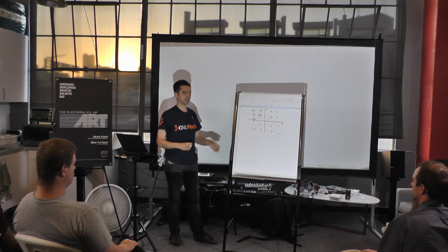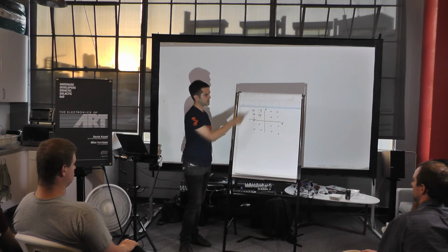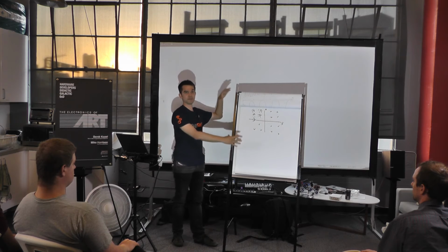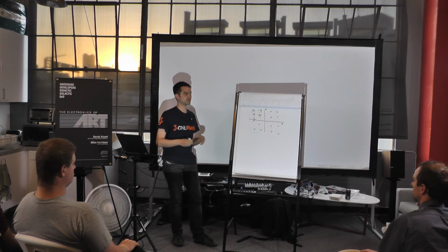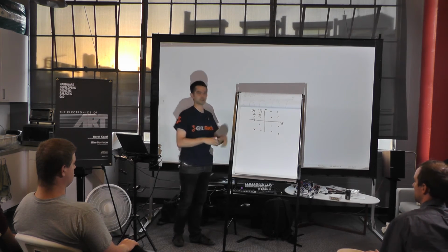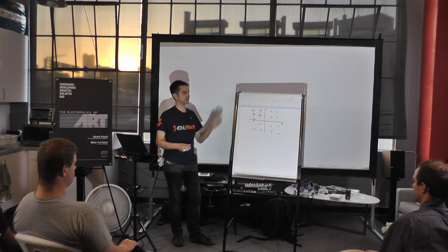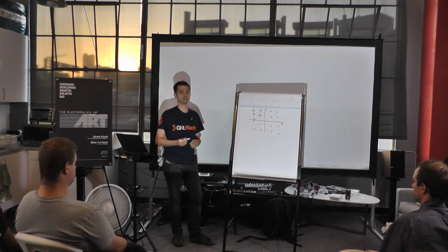And so they do lots and lots of fancy tricks to make sure that this doesn't happen. But it's reality, so it does. You make mistakes, and you guess the wrong one. And all of a sudden now, when you have a lot of information packed into a single symbol, you're not just getting 1 bit wrong. You're getting 5 bits wrong, 10 bits wrong. And so they do a lot of smart things to try and minimize that and transmit redundancy and all that. But they've gotten up to constellations where you have 1,024 different points or more. And that starts getting very, very dense. But it gets you your YouTube video really, really fast.